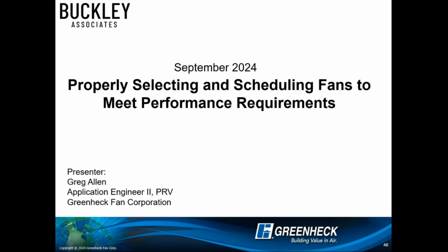When we were looking at static efficiency, we were seeing that it was only going up to about 60% efficiency on that selection, and she's asking, that seems low, and therefore a poor fan selection if efficiency is a priority. Is that true, or is 60% static efficiency pretty normal?